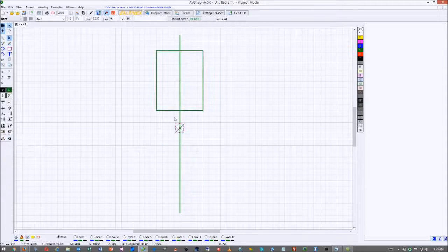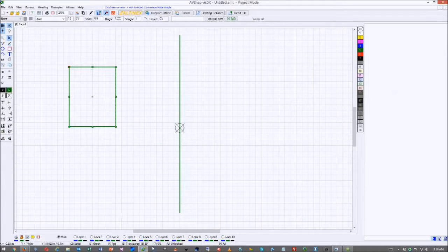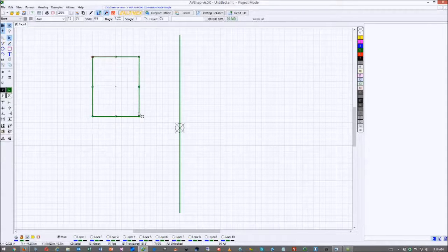So the same thing we do with rotation. If you take the object, and I'll put right now 5 degrees rotation just to give us a better understanding. Pressing space bar rotates it to the right. Shift space bar rotates it to the left. So I'm going to go ahead and space it. But what if I want to rotate it around a specific point?